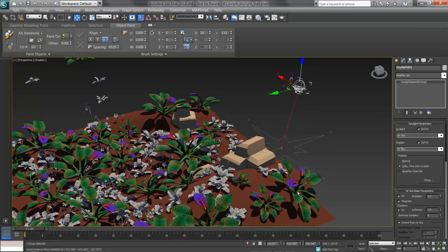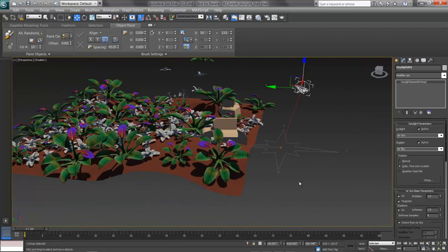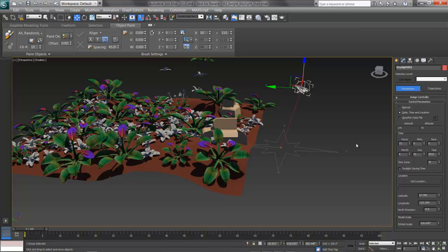Now what I can do is reorient it. At the moment, it's not terribly exciting, and I can tell this from the angle. I'll jump over to the Motion tab, the wheel here, and move the daylight around. What we want to think of with our daylight, and we have a very good ability to do, is where is it and when is it? As we can see right now, it's noon on June 21st. That's the summer solstice, the highest, straightest point of the sun in the sky, although it looks slightly angled.